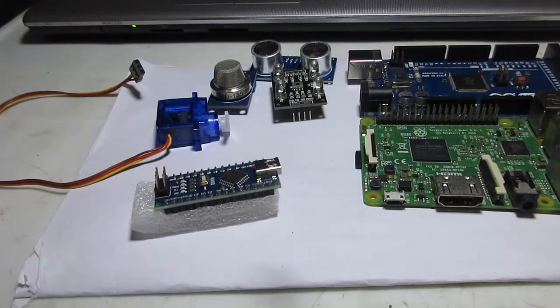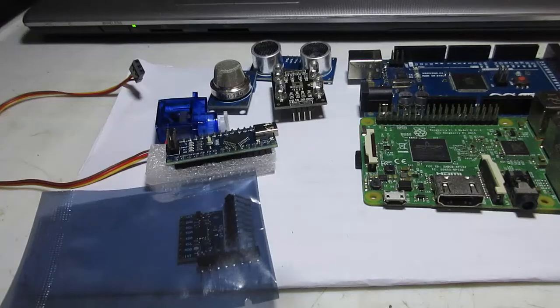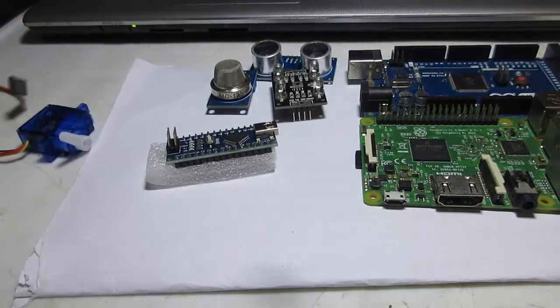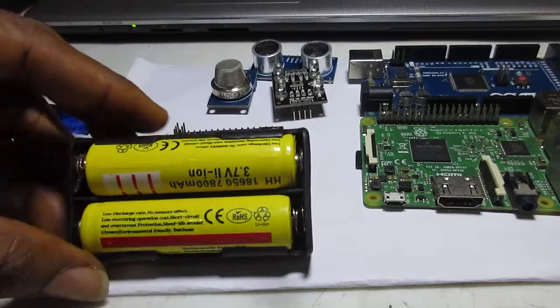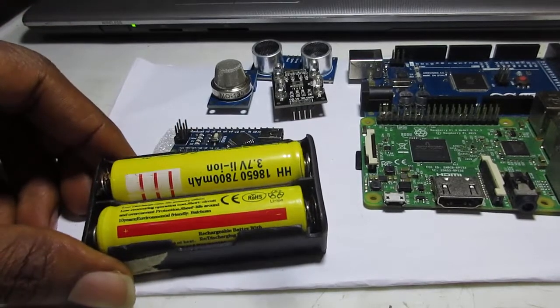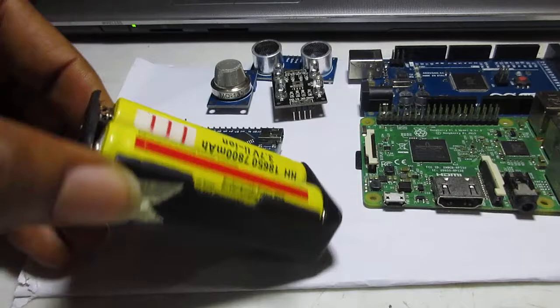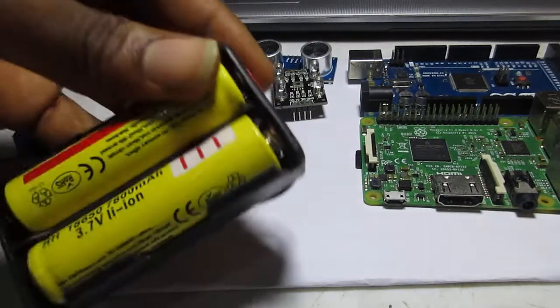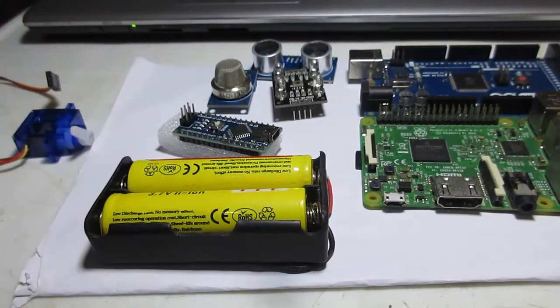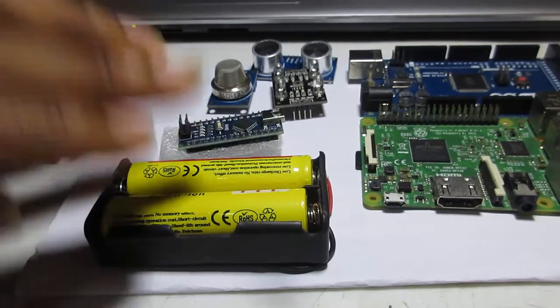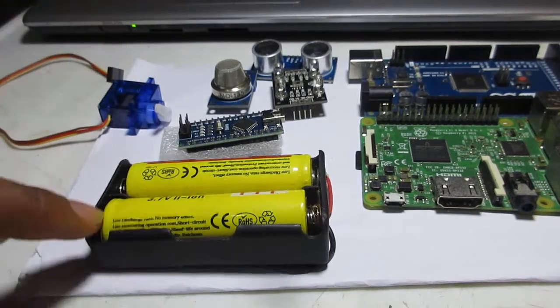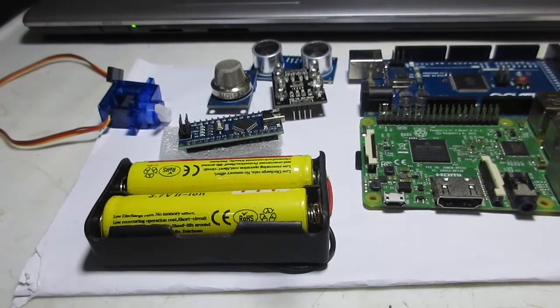Alright, I'm going to be wrapping up my class now, since you've already seen the models. The last thing I'm going to explain to you is the battery. I think most people don't know that the battery is very important when it comes to building robots. And this battery is a lithium-ion battery. It is actually a 2S battery, and this 2S is about 4.2 times 2, which is about 8.4 volts. If you want to make a project, you need a lithium-ion battery to get started with, because it powers your robot very well, unlike using your normal 9-volt battery. So I will advise you that for any robot you want to build, try to get a lithium-ion battery to work with. It's really going to help you.